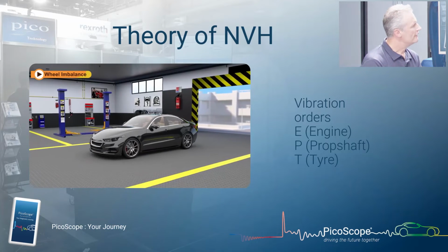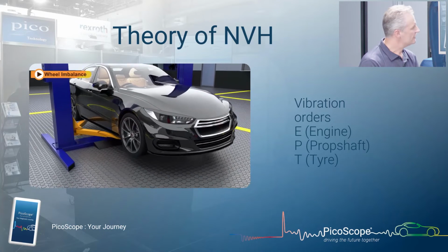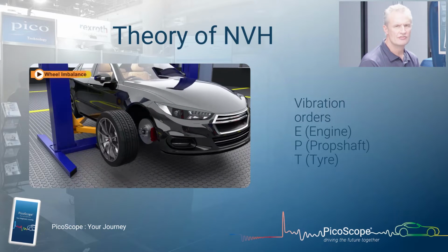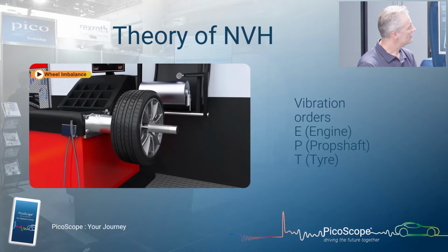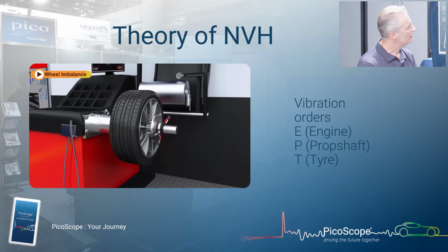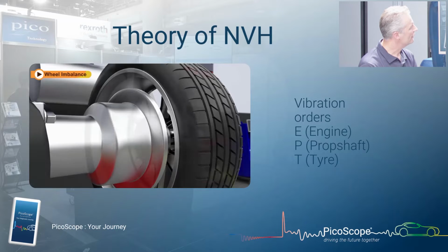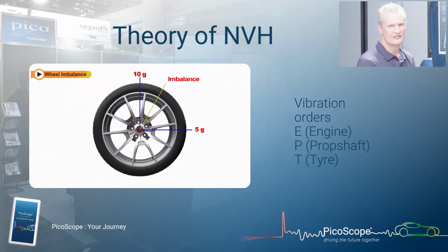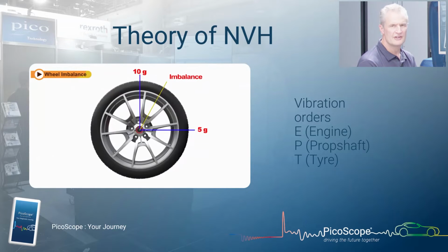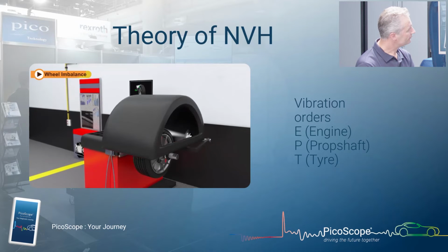Yeah, so here we are with the wheel balance procedure, and highly recommended is road force balancing. You'll see this machine here, how it applies a roller to the tyre, so it actually compresses the tyre and simulates the deformation that would be on the road.